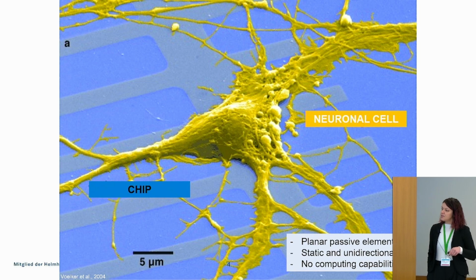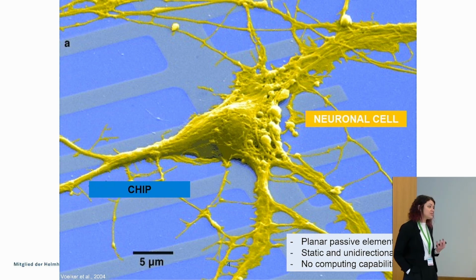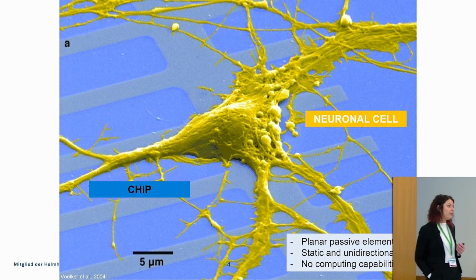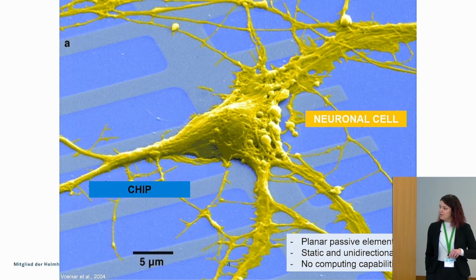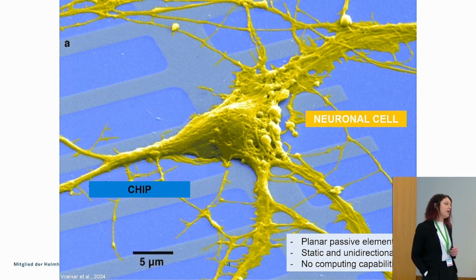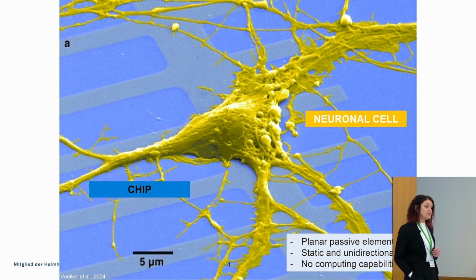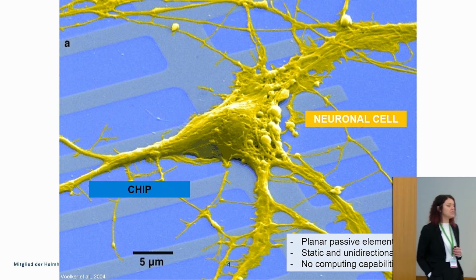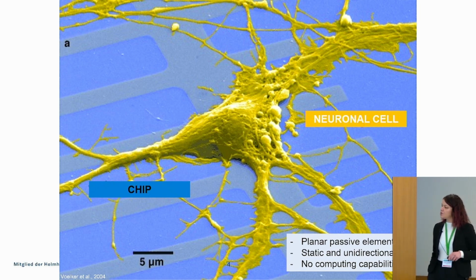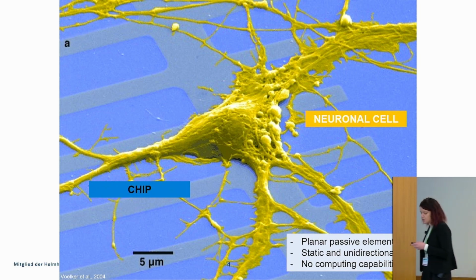And then this is the typical behavior, which very strongly depends on the capacitive behavior of the conductive polymer itself, which can be represented as an RC circuit. The rise time, or response time, of this transistor channel strongly depends on geometrical factors, so length and width, for instance, or thickness of the PEDOT channel, which also affects how this capacitor is charging and discharging.